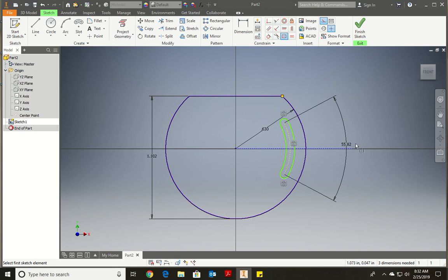By doing that now, if I were to change the dimension, like so, to the correct number, which is 30, right? It's going to place it in the middle. Now if I didn't do those constraints and I undo it just to show you what happens, watch. Now I don't have the center line, or we can just go back.